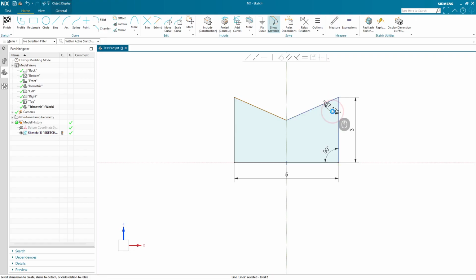So let's set this angle really quick. We'll set this angle to 60 degrees. Let's say we want to do another equality constraint, but we can't directly get this angle. We can set that the lengths of these two have to be equal. So now we have a fully defined sketch: the lengths of these two are equal and the lengths of the outer two are equal, so this angle has to be the same here and here, and then this angle has to be symmetric around that center line.